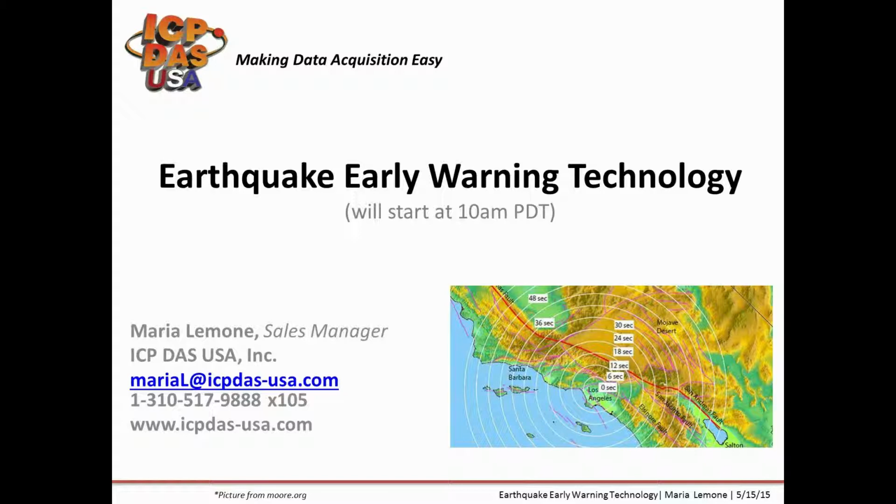Today we're going to be going over earthquake early warning technology, which can save lives, prevent injury, reduce disruption to critical activities, and protect resources. Seismic switches and control and monitoring software can be used to implement automated actions like alerting drivers approaching bridges that could collapse, open doors that are normally closed to allow people to get to safety, stop elevators that could break and snap during a strong earthquake, turn on audible warning alarms and lights, close gas valves, open firehouse doors, alert school children to take cover, and alert doctors to stop delicate procedures seconds before shaking begins.